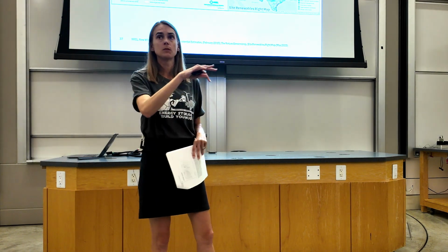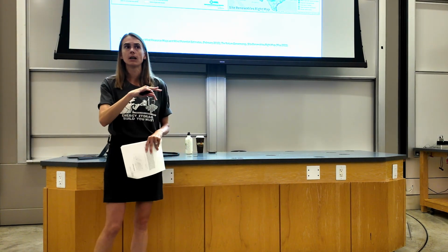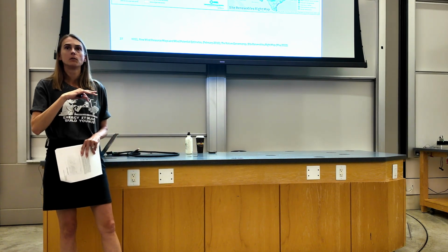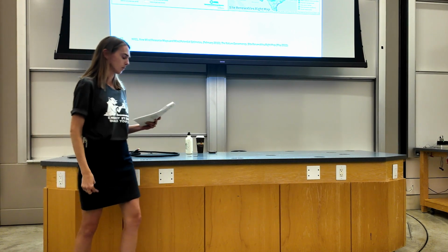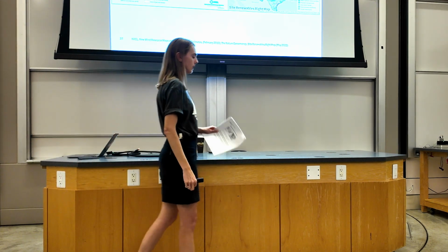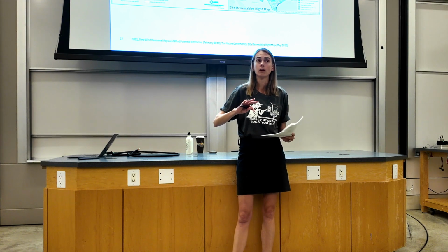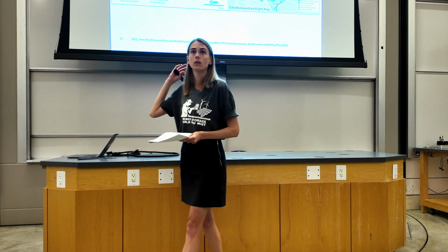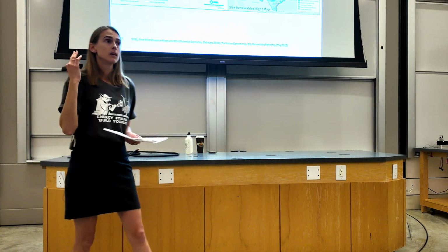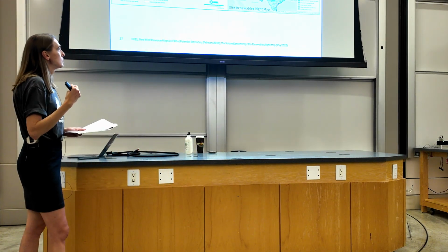Another big consideration with site selection, we talked about proximity to population. Oftentimes, different municipal areas have setbacks within which a wind project has to be sited a certain distance away from where the population is. But also importantly, there are environmental constraints to consider. We didn't talk about that during our brainstorm.